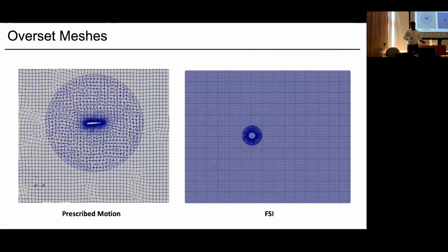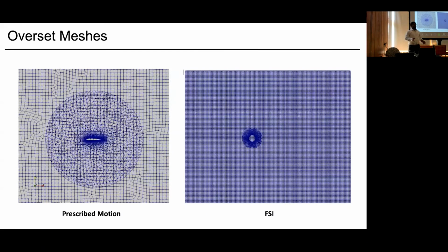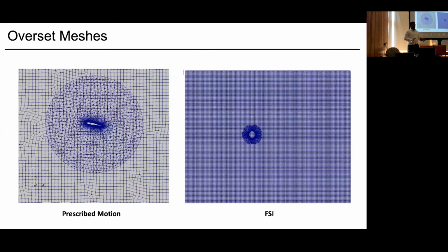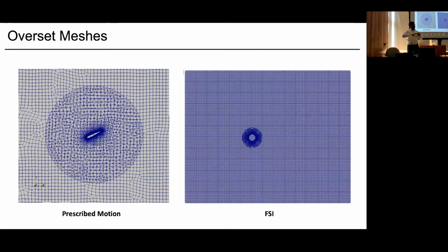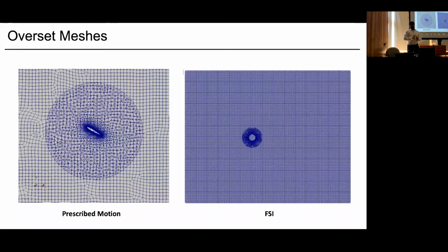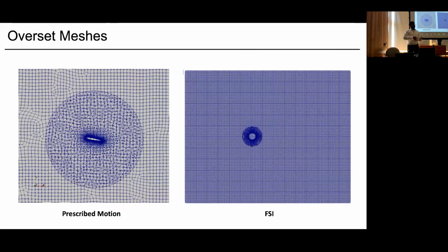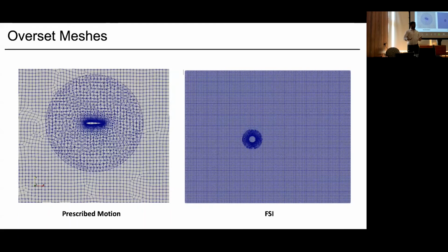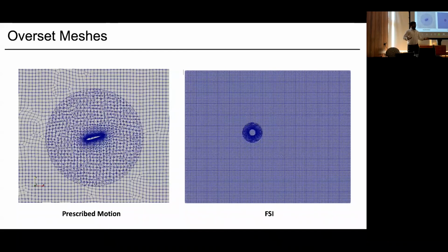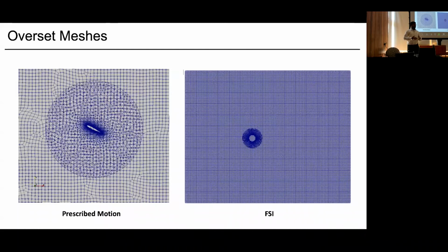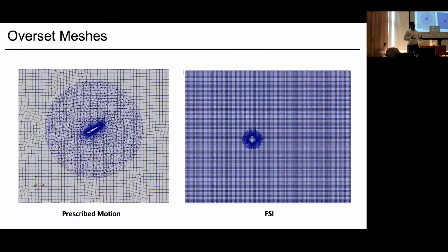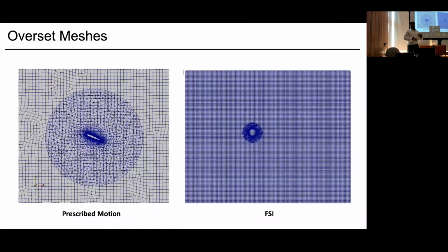Basically, in this case, in the prescribed motion, you prescribe the similar motion functions on a body and the overset mesh on the cell zone, which moves in an Eulerian grid. And you can also simulate the FSI problem very easily, right? There is no mesh deformation. So ideally there should not be any problem as long as your accuracy is good.